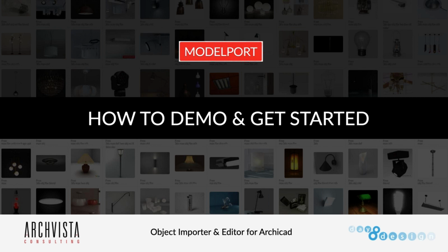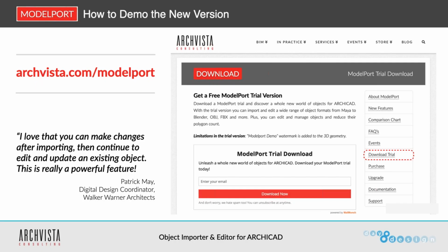Now, if you want to set it so it's more universally available to anybody, not just someone who has ModelPort installed on their machine, you can always set it to GDL, which would not, of course, have the compression and not have the ability to edit the object. Or you can set it to GDL and ModelPort, which kind of gives you the best of both, meaning it does compress and it does allow for editing options, but it doesn't compress as much, which means that if you add the 2, it doesn't really change the file size too much. It's really more about just maintaining the editing options.